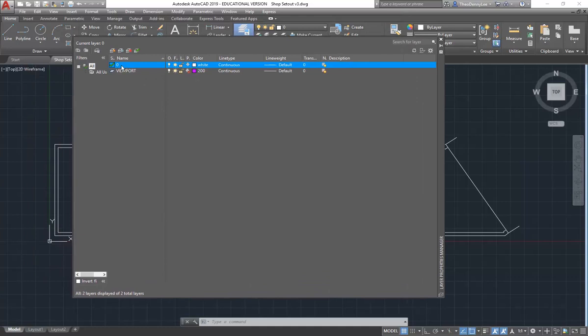The difference between AutoCAD and Photoshop, though, is that the order doesn't matter. They don't stack up on top of each other like in Photoshop. They're all basically at the same level. So it's just for grouping things, which is really helpful. When you bring up Layer Properties, it's this button here. It's the first in that group of 4 little buttons that makes a new layer.